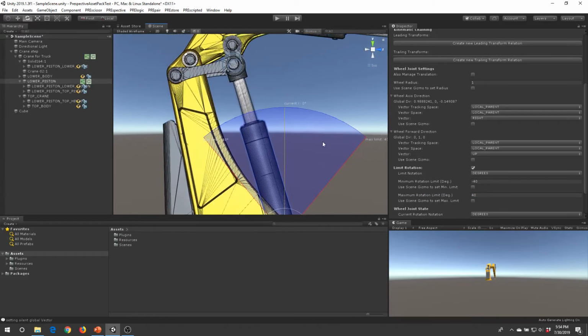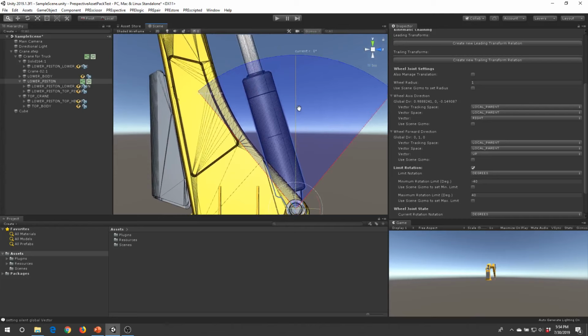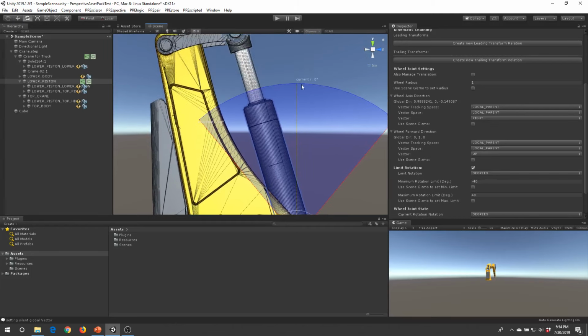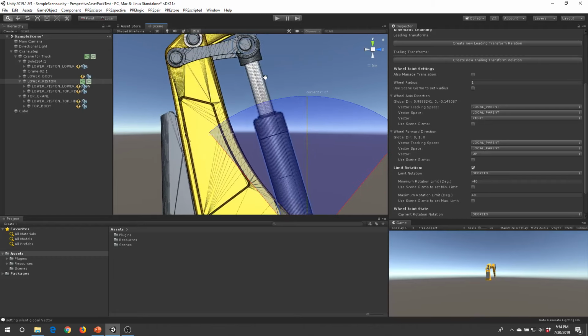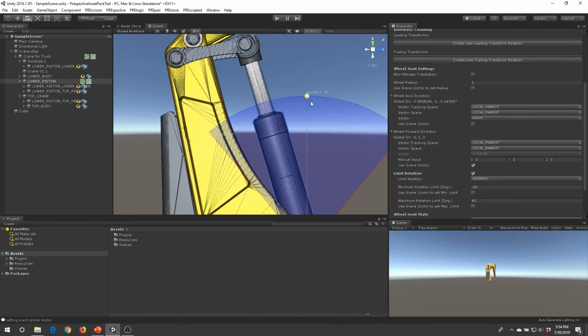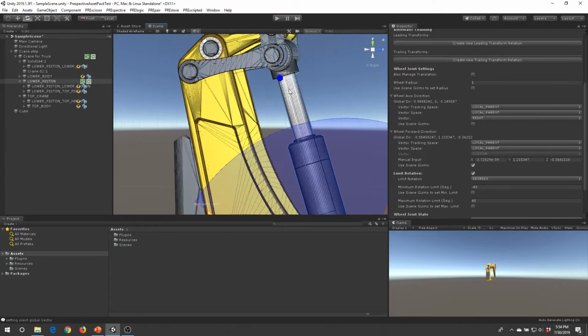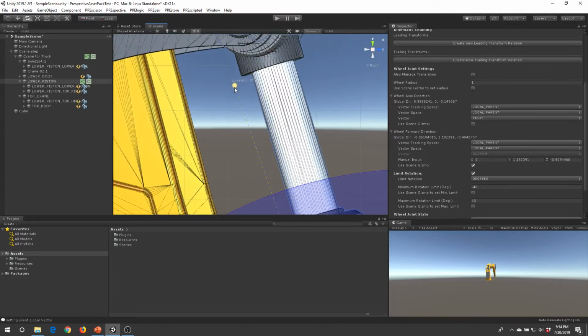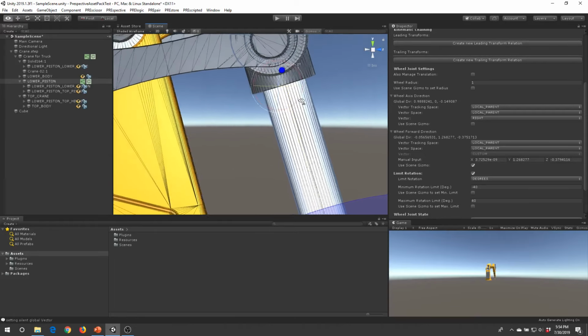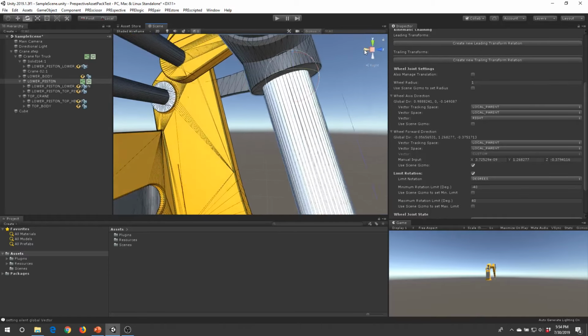You'll see now what the effect is of the directional change. Also, you might want to say that the actual forward direction, or the 0 degree position of this joint, is in line with the piston. So you might want to use a gizmo for that. That's actually the forward direction, so we'll use the scene gizmo in the forward direction. Now I'll get this gizmo over here, and let's align this neatly by using vertex snapping. So I'm just going to press Shift V again, and you'll see it's going very aggressively into the system.